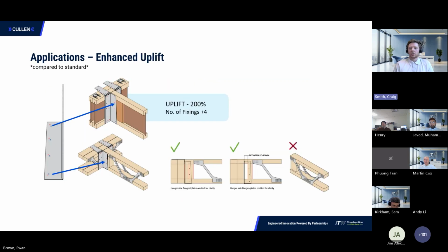With the HUH, we can go to enhanced uplift. So we're adding 4 nails into the triangular holes on the incoming member. With an I-joist, we'll be using a web stiffener. For metal web, we want to potentially insert a bit of timber that's the full width of the joist, and that could be 20 to 40 millimeters forward from the rear of the hanger, just to ensure that we have some material behind those nail holes. The extra nails equals increased uplift. More nails, more load.